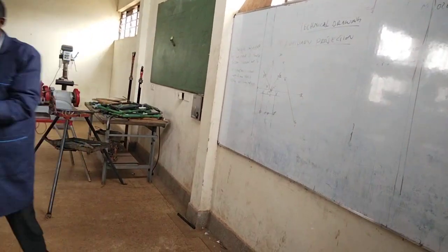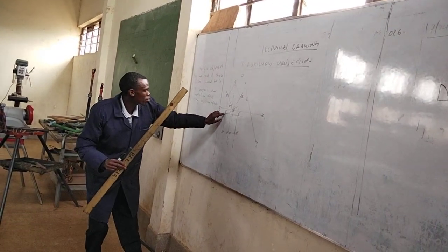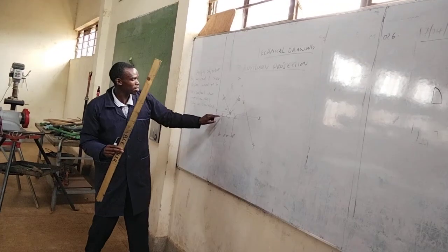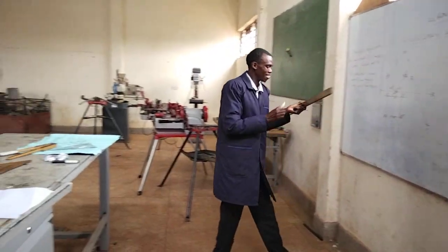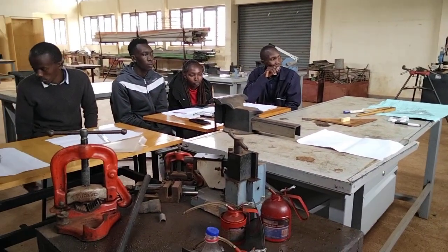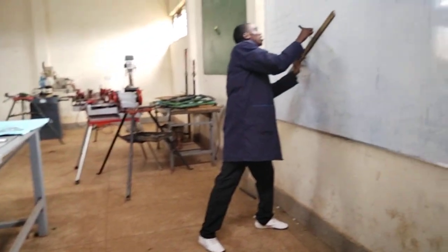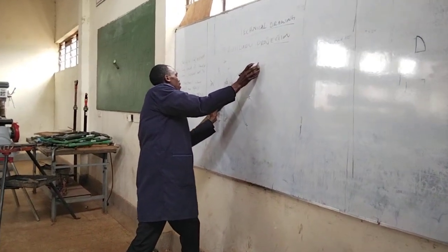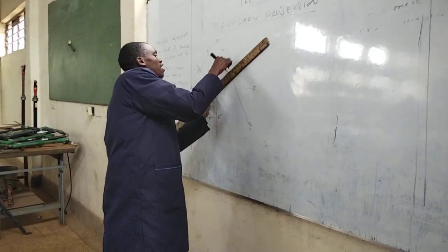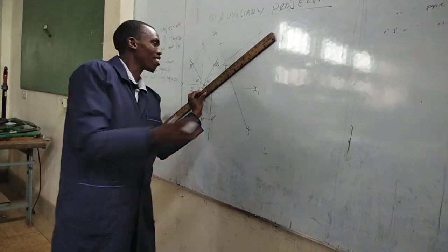So what will you do? You project these points, starting from this one, and make sure the line you projected from this point to this line is perpendicular to this line. So make sure, and that one, project all corners. So make sure this angle should be 90. Okay.